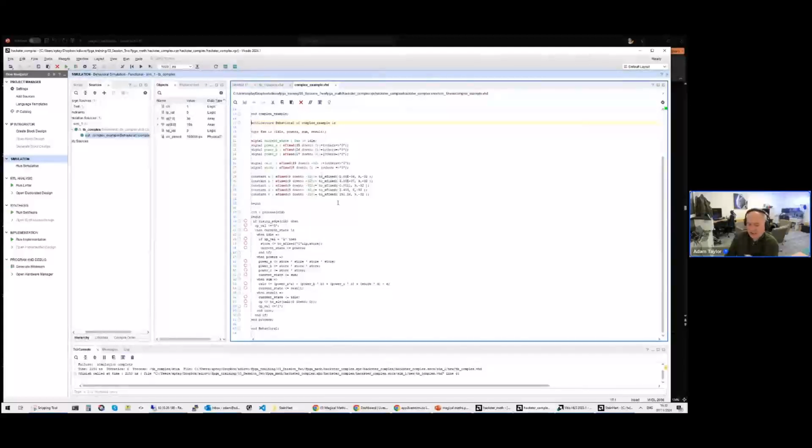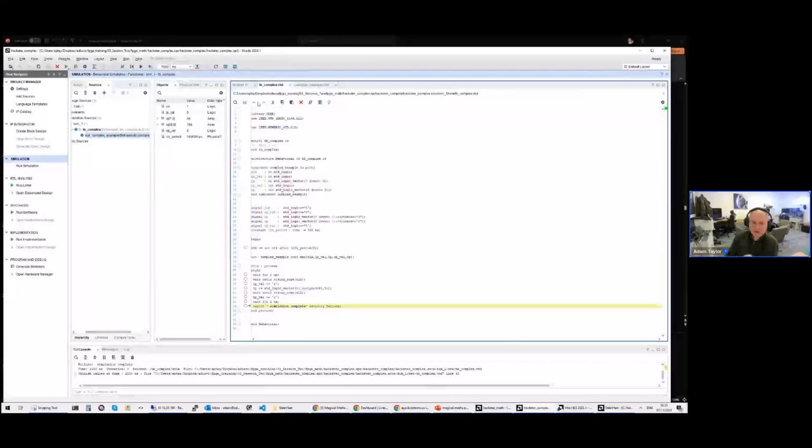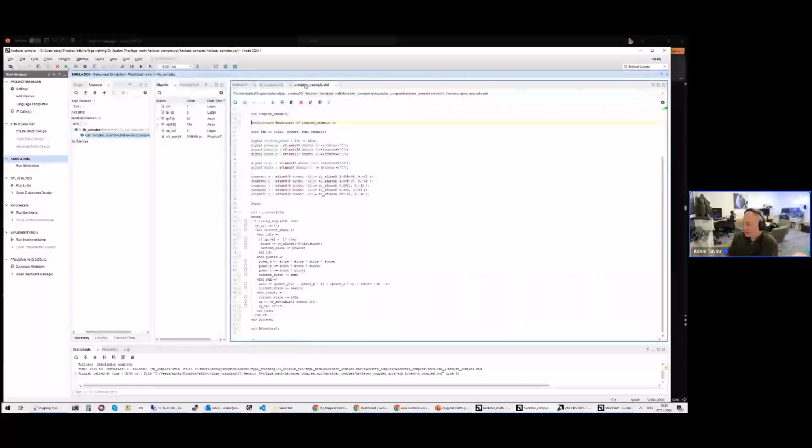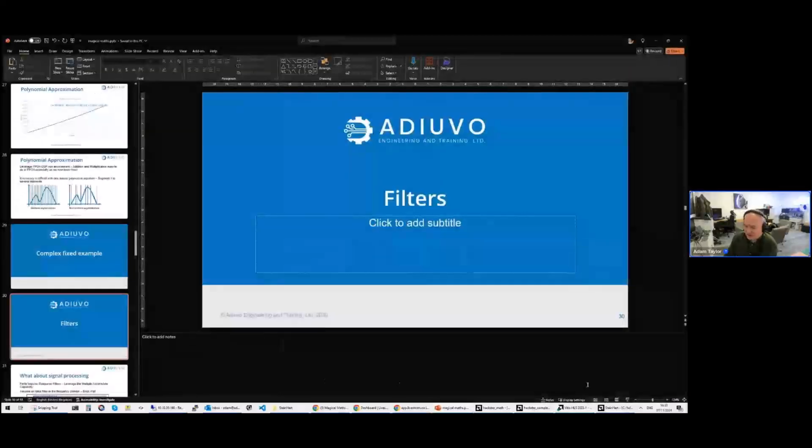We've used the quantization, and then I've used a simple little state machine just to run around and drop it out. What I will do as well, there's a spreadsheet with this which shows all the calculations for it. I'll provide that. And there's also a test bench. You can see it gives you a little bit of code that you can simulate through and look through. So there's a nice example there of how you can do that complex FPGA algorithmic implementation using polynomials.